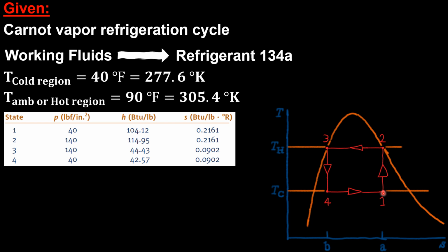When the working fluid exits the evaporator, it is mainly vapor, but it has some liquid. Having a liquid in a compressor is not a good idea, and that's why the Carnot vapor refrigeration cycle is not a realistic cycle, and that's why I said in the beginning we can use it as a benchmark only.